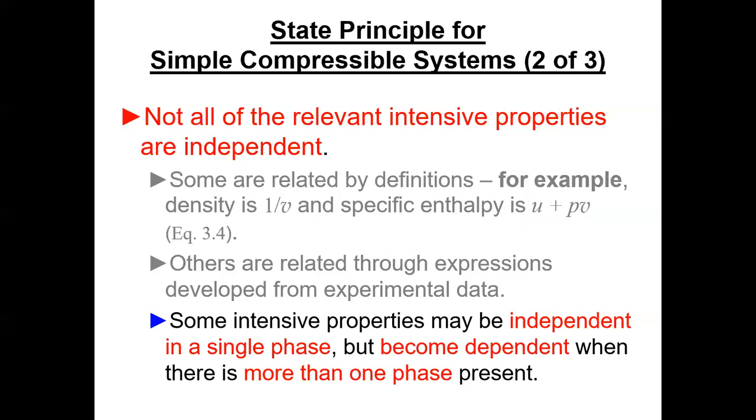And so if you're boiling fluid on a stove, you can't fix a state with temperature and pressure because they're not independent. Okay. If you're just heating water, then yes, temperature and pressure are independent. If you're heating ice or you're heating a gas, they are, but if there's a phase change going on, then they're not. So we just have to be careful in how we select these independent properties, that the ones we choose really are independent of each other.